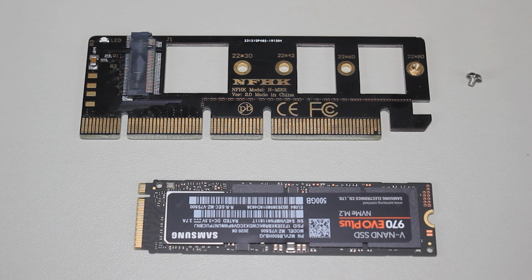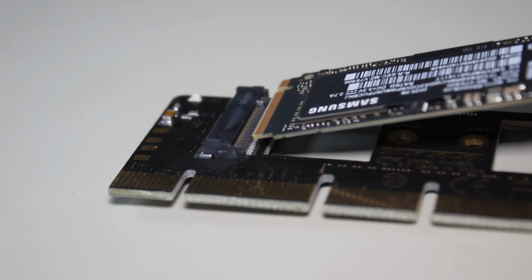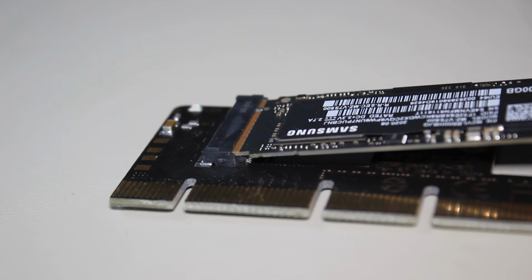This PCI adapter board only supports PCI Express M.2 devices. Although possible for either to support both, due to the extra difficulty and cost of supporting both, you will generally find that B+M supports SATA and M supports PCI Express. Thus, make sure when you purchase an M.2 SSD, you purchase the one that is compatible with your computer. The next step is to plug the M.2 SSD into the adapter. The process is the same if you were installing it on the motherboard.